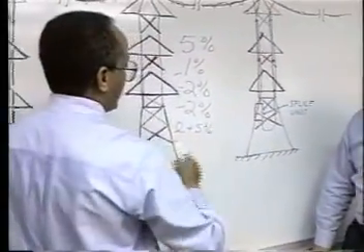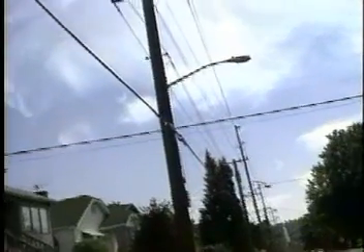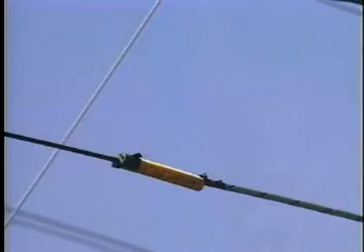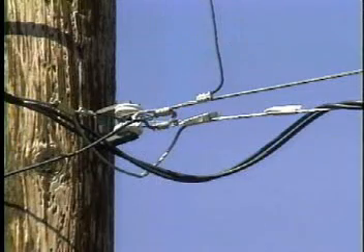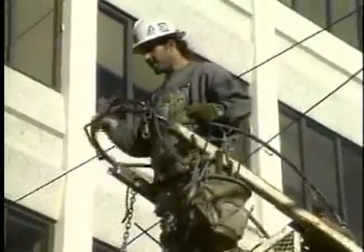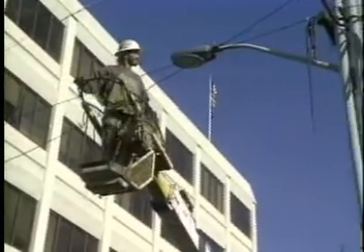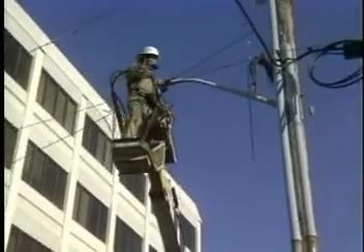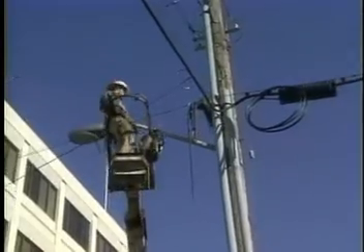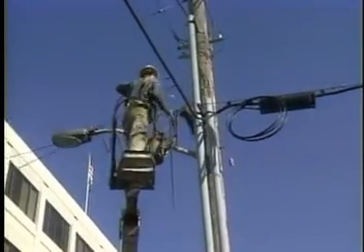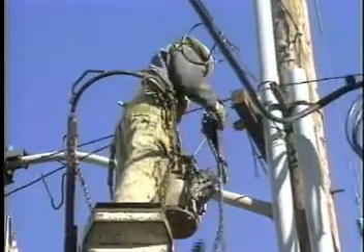With any type of aerial installation, the following considerations should be kept in mind. Fiber optic cables should be clearly marked periodically along the route. At pole locations, a drip loop should be employed to allow water drainage off the cable. When working near energized power lines, be aware of the safety hazards posed by induction and flashover. Be especially careful to remain outside the minimum approach distances as outlined in National Electric Safety Codes.